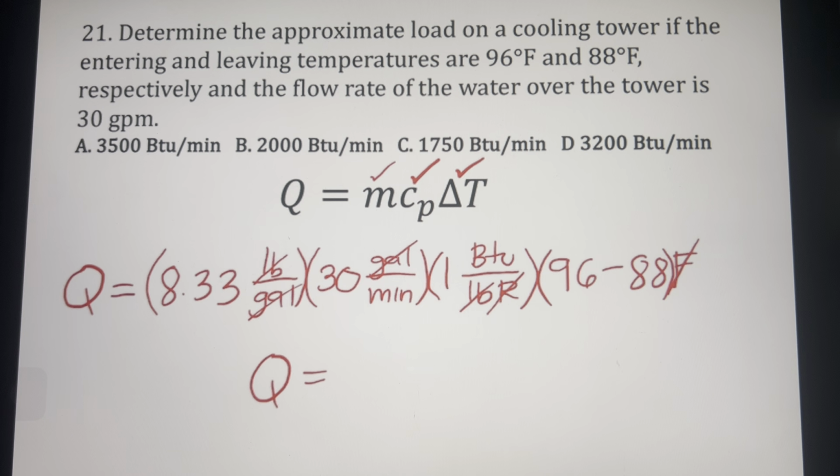So from the ducting's lecture video, we know that the equivalent diameter given the dimensions of a rectangle is equivalent to 2AB over A plus B, where A and B are the dimensions.